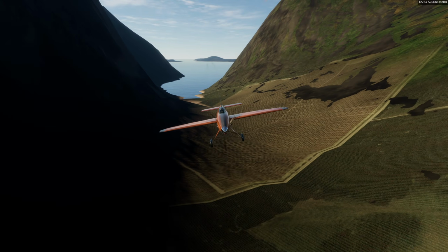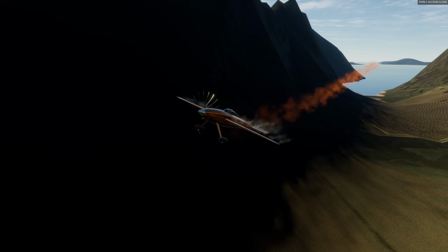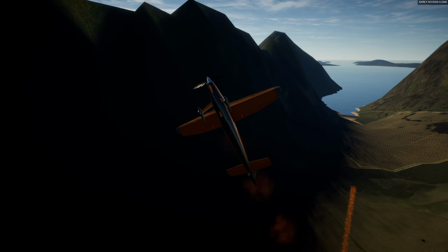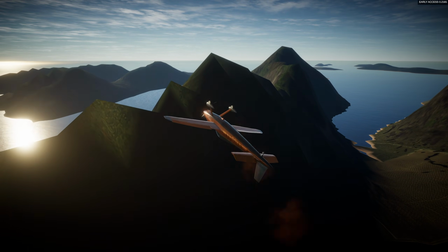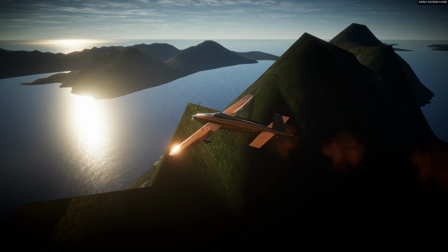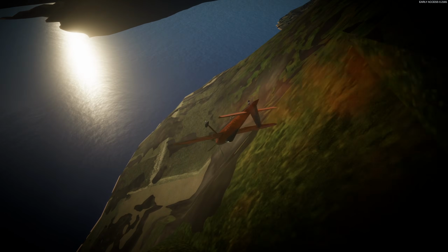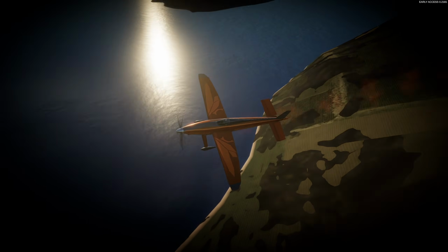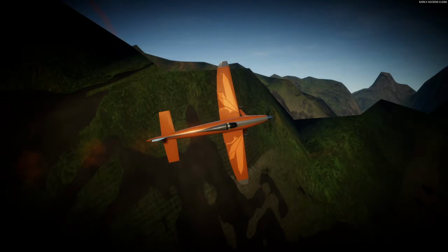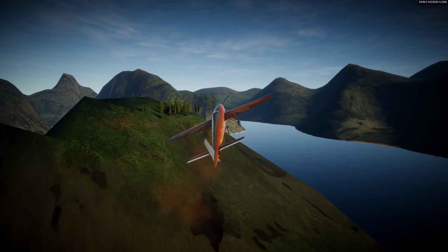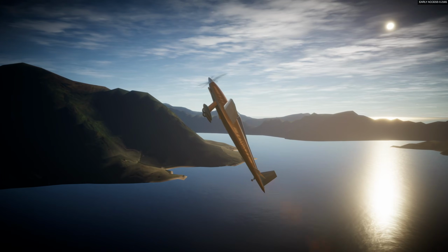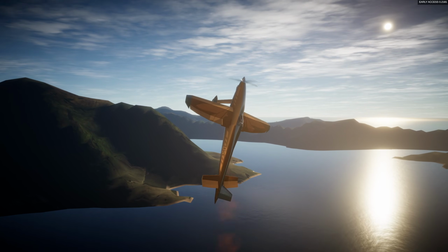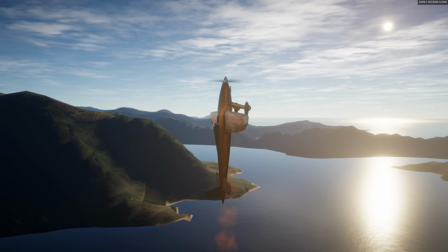If your propeller spins slower than Mach 0.8 to 0.9, you may be losing out on some thrust, although this can be fine for making very early aircraft realistically. If the propeller spins too fast, it can also lose out on thrust due to the propeller airfoil reaching its critical Mach number and losing effectiveness due to the appearance of shocks. To provide ample power to the propeller, the engine also needs to be spinning at its own optimal RPM, as mentioned earlier.